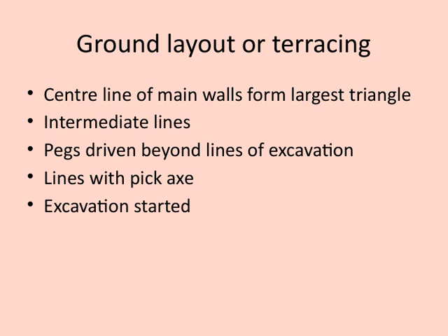As you can see, the center line of the main walls forms the largest triangle, which helps us establish the overall framework for the excavation. The intermediate lines are then added to break down the area into manageable sections. Pegs are driven beyond the lines of excavation to serve as reference points, ensuring accurate placement as we proceed. Lines are then marked out with a pickaxe, which helps us maintain precision when outlining the boundaries.